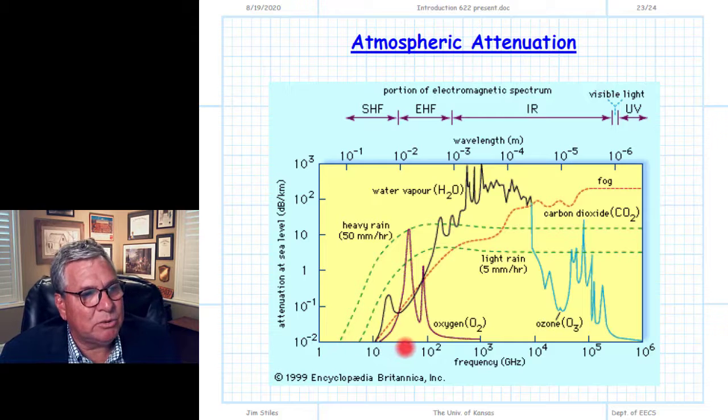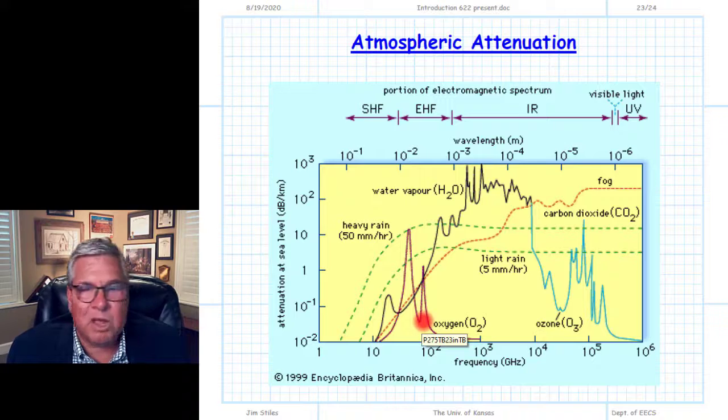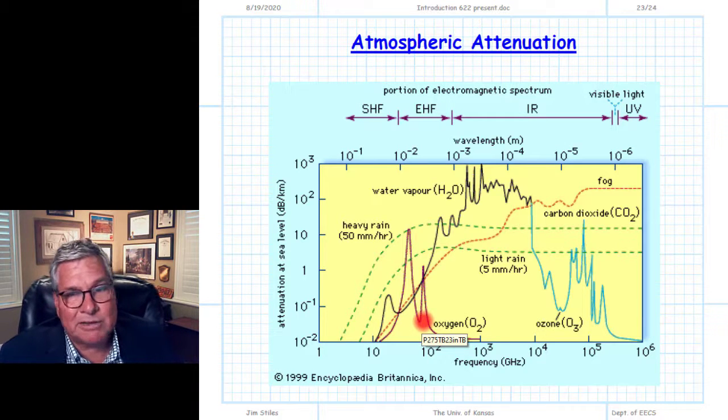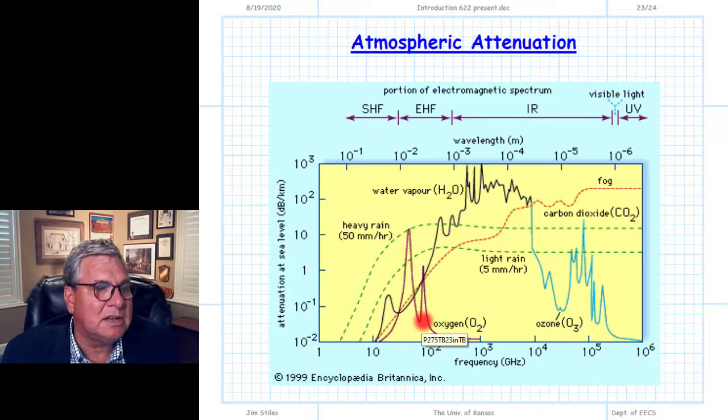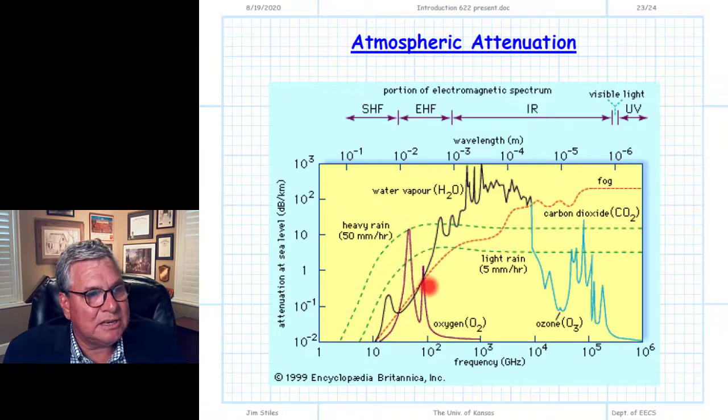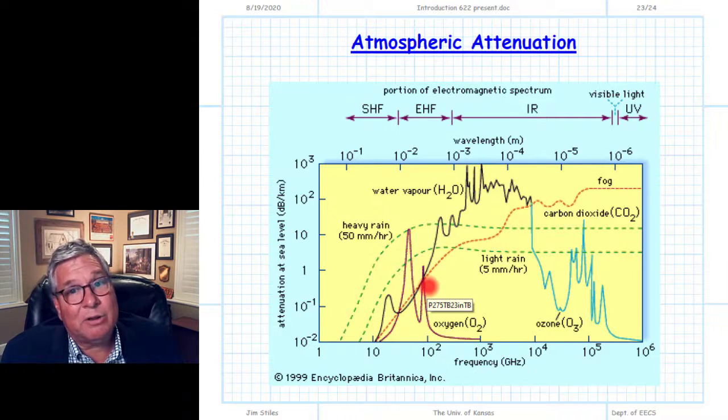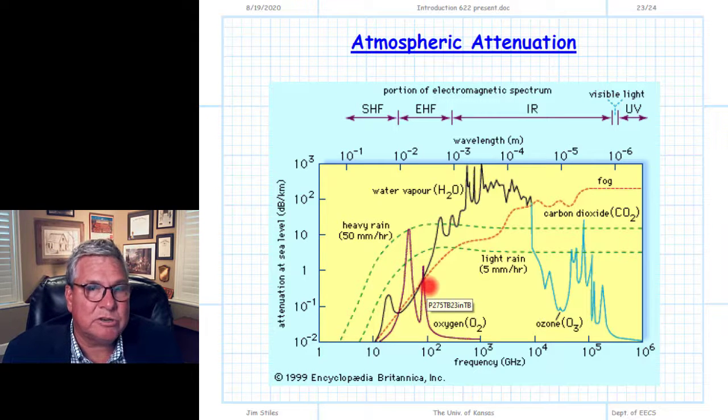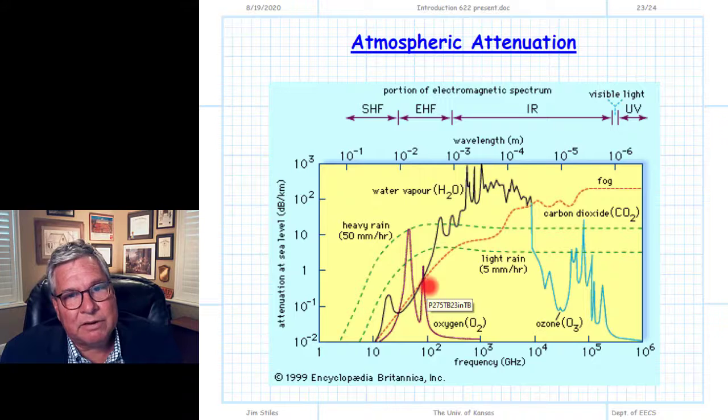But as we start to move up into the gigahertz region, tens of gigahertz, 30, 40, 50, toward 100, we start to see that there's this peak in the attenuation. So these are what we call absorption lines, and this really gets back to quantum mechanics, where the energy absorption can happen for certain frequencies. At certain frequencies, they not only can absorb energy, they will absorb energy at a great rate, and it becomes very difficult to propagate through even a very short distance at those frequencies.